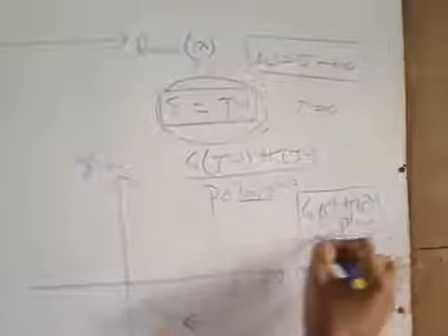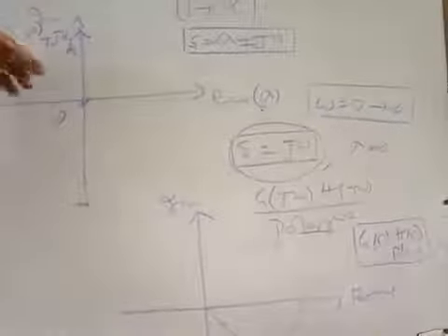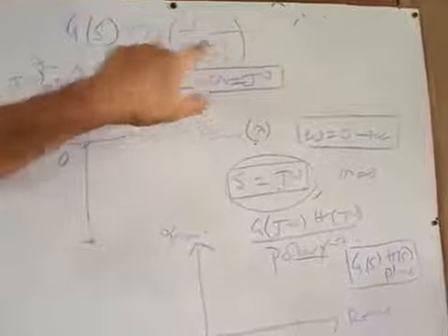Here we are going to discuss the conformal mapping theory. What is that? Omega is varied from 0 to infinite, that means in the s plane you are varying the frequency. For each s, jω and H(jω) vary because it is a function of s. Once this is varying, you get the polar plot.